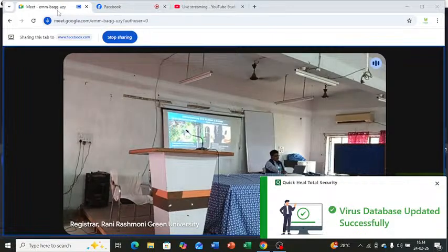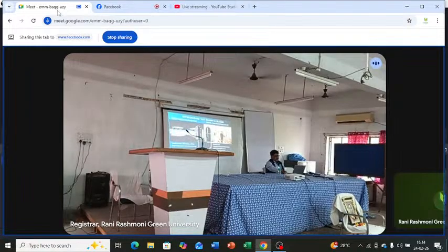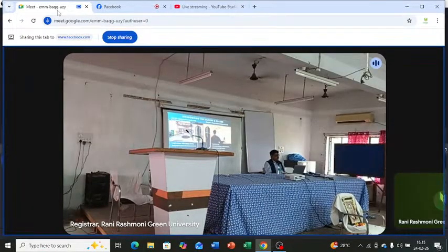Now, the same version is hand carried. This is called Go. It has a lot of cameras, in fact 3 cameras, and it can take up to 4,20,000 points per second and a maximum distance of 25 meters. Okay, so how does it work? As a person is moving, it is scanning around it. And most importantly, these scans are merging with each other automatically. There is no separate georeferencing required.